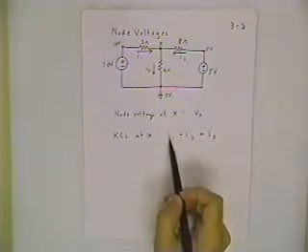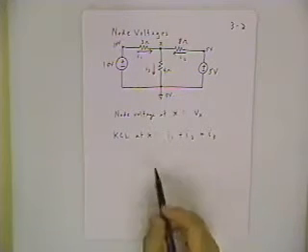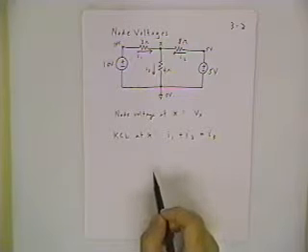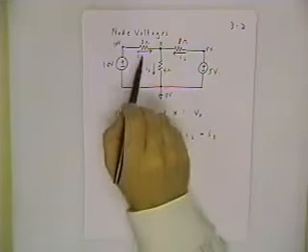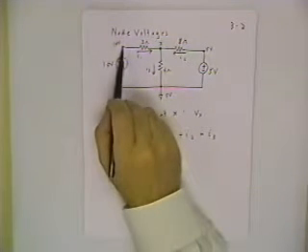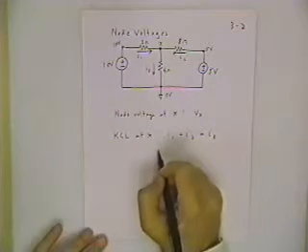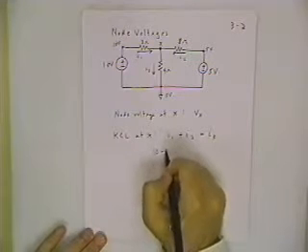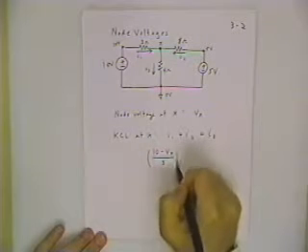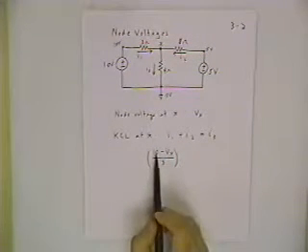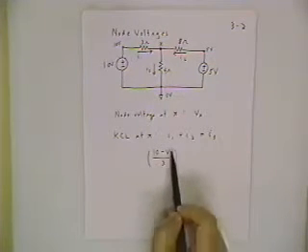Now remember that the current in a resistor is the potential difference across that resistor divided by its resistance. That's what Ohm's law really means. The V in V equals Ri is a potential difference. So for this current I1, the potential difference is 10 volts minus whatever V sub X is. We can just write that out as the unknown expression: 10 minus V sub X, divided by 3. And look at the units of what you have here: 10 volts, V volts, 3 ohms. This is volts divided by ohms, so you've got an expression here for a current.